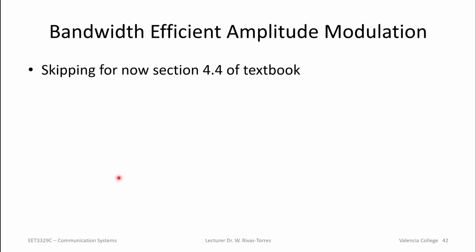So you still have maybe somewhere around 25% of the other sideband that you don't want. But that is still better than sending the whole thing, right? You don't have to send the whole bandwidth. And when you think about how crowded things are, it lets you put more stuff, especially when you're doing FDM, frequency division multiplexing.